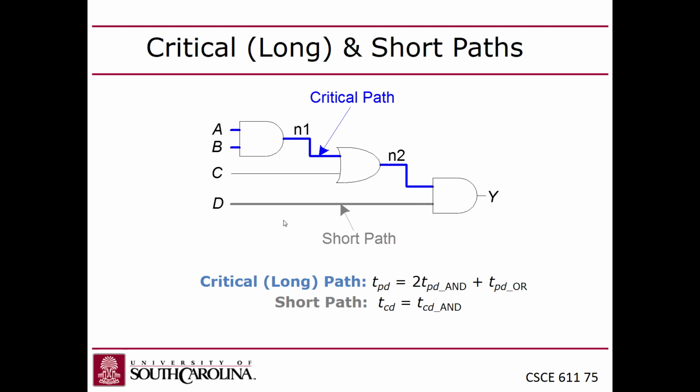It becomes really slow, and it's also more cost effective to have a simpler standard cell library with just a small number of gates. So as a result, you have to trade off. You have to say, well, I can't go through 2 levels of gates, so I have to essentially apply the Boolean theorems to convert what could be done as a sum of products into another form in which you potentially will have to go through many, many gates before you get to the output. You guys with me? Okay. So now there's a side effect of this called glitches.